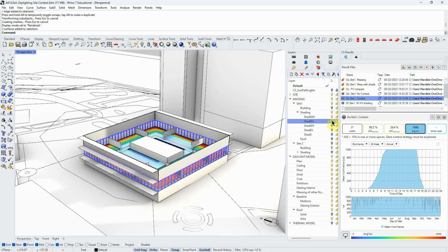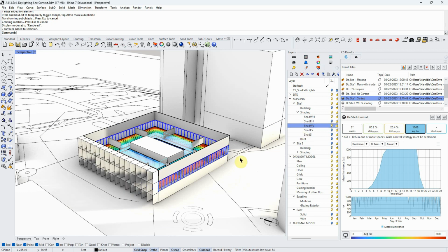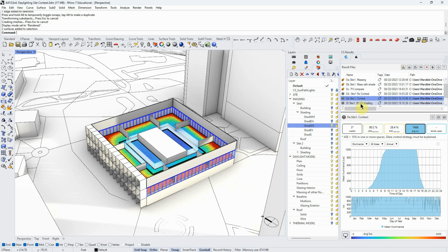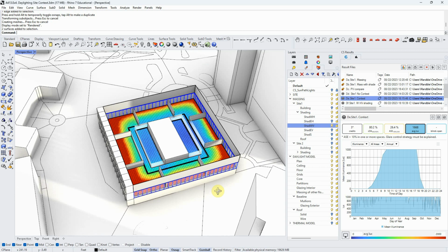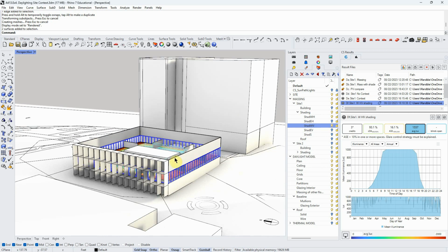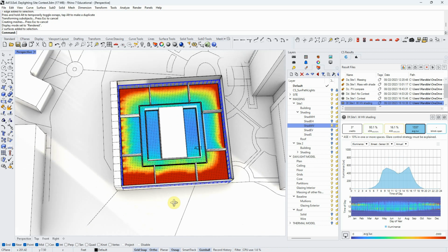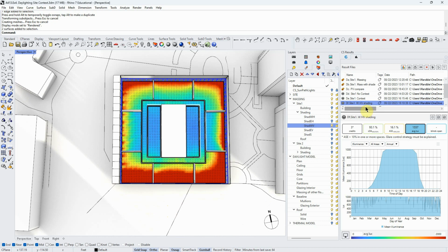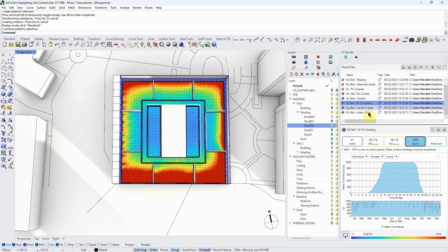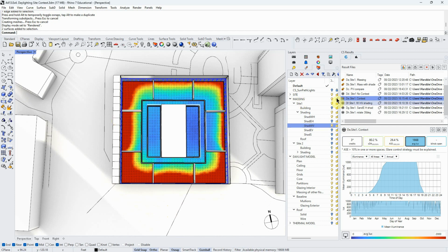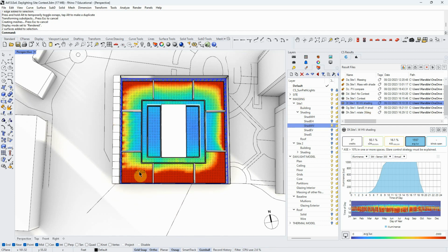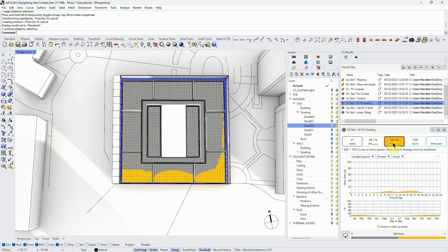So the first thing I did was, and we can see here, I have just the west horizontal and vertical shading. In other words, I have shading on the west side, but none on the east side. I'm going to switch back and forth between the two. So without the shading, I'm here. By adding this shading on the west, and again, I need to dial in more, I can look at this. This was just the average lux. This is the LEED 4.1 annual solar exposure. And so the yellow places are where we're overlit.